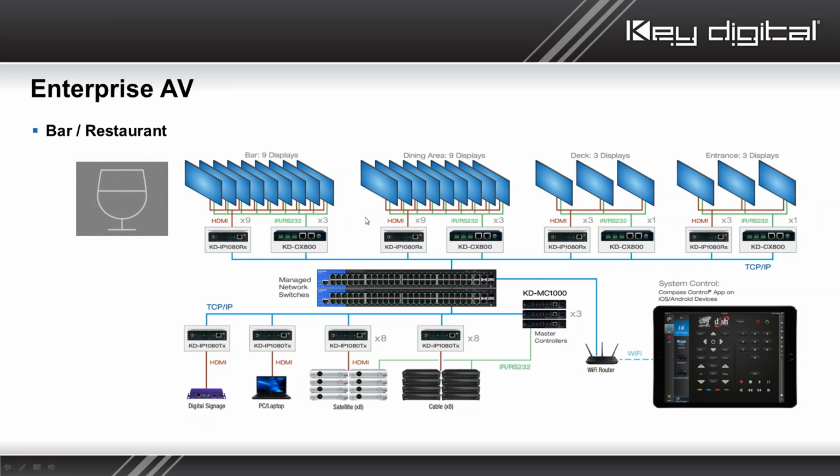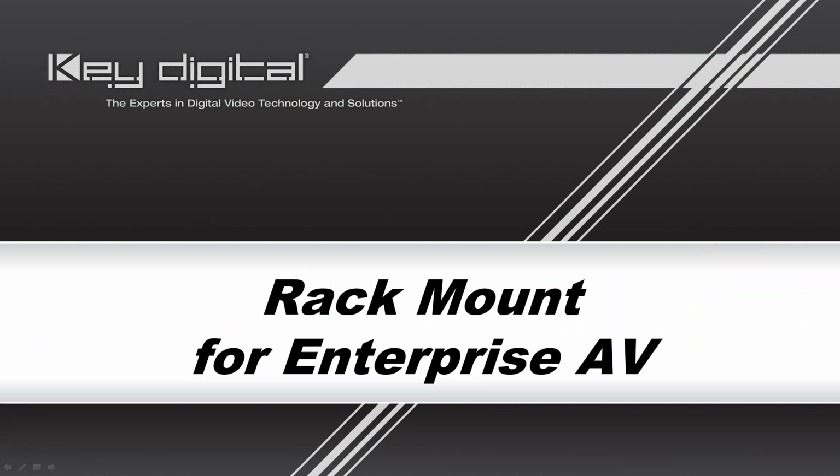This uses a different compression method. It's H.264, which is extremely low bandwidth, so we can have very large systems here using multiple network switches, and just use the fiber uplink port at 15 megabits per second. Each encoder, you're never going to exceed the bandwidth of your fiber uplink port for stacking 2 network switches. We've even had folks install network switches at various locations throughout the building, even using Cat6 as the link between, but you'll want to talk to your network hardware manufacturer for that.